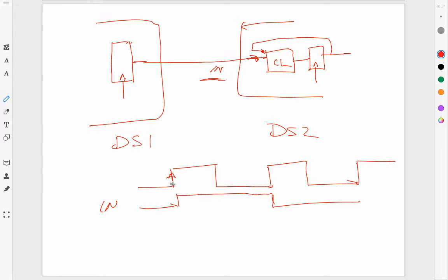But what is really happening out here? It is changing a little bit after this guy. There's going to be some tiny time delta. And likewise, when it changed out here, there will be some tiny time, another delta prime, let's say, that delay can change. Agreed? So even though n seems to be changing at that clock tick, it's really changing a little bit later.